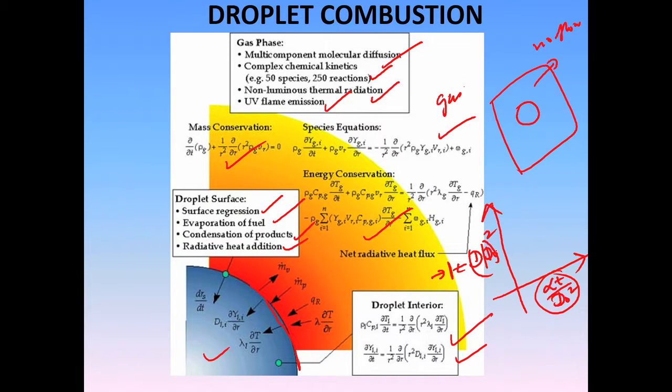Perhaps they took a camera and monitored how this droplet is evaporating. So, they were calculating the droplet diameter at each time instant. After they were done with that, they squared the diameter, divided it by the initial diameter square, and plotted it. What they saw was that it will always go from 1 to 0, because the droplet will always shrink, and this is an evaporation case. Let us not consider condensation. They got a straight line, a linear profile, no matter what fuel they used.